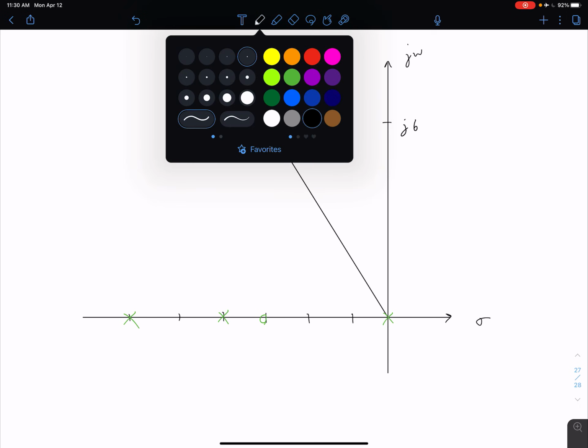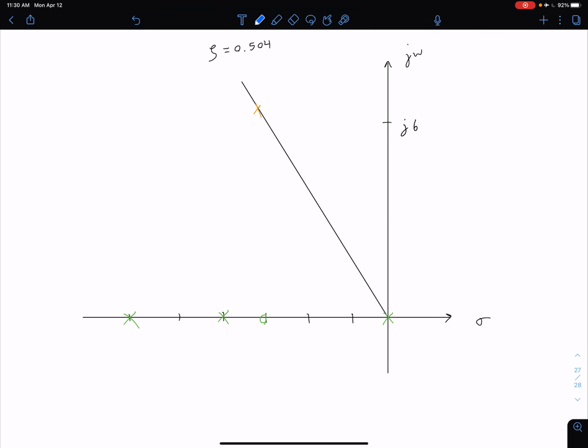So let's switch over to blue, and we know on our real axis, it's going to be on the axis between 0 and our... have I forgotten a 0? No. So it's going to be between here, between our pole at 0 and our 0 that we inserted at -3, and it's going to be on our real axis between here.